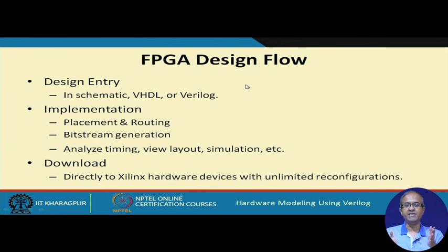So, in FPGA you say everything is programmable: the logic is programmable in terms of the lookup table, interconnection is programmable in terms of the switch matrices, and also the IO blocks can be programmed. So, when I say that in that board I had shown earlier that I am downloading some data on the FPGA board, we are actually downloading all this programming data. Depending on my circuit net list, the synthesis software will be generating this programming data, and if I download it on my chip, I will be getting my desired functionality on that chip.